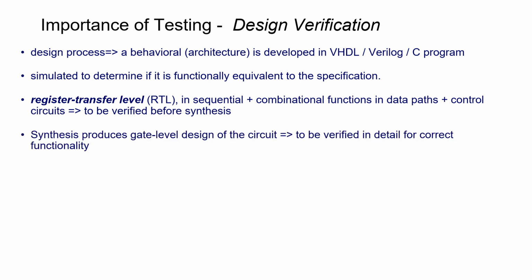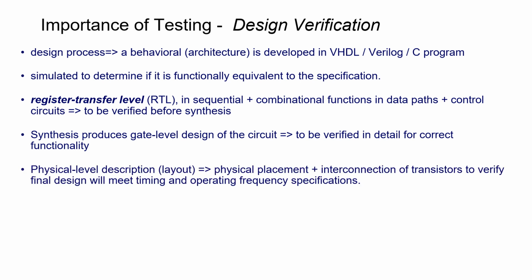So synthesis produces a gate level design, as we saw in the making of a chip in the first intro class. The synthesis takes the RTL as an input. It takes the technology library as an input. It takes the constraints as an input, and it verifies the correct functionality. And so that transforms into a netlist. A netlist is just a connection of gates and flip-flops using wires, and it connects them to the VDD or ground supply signals, optional if needed. And we do physical design.